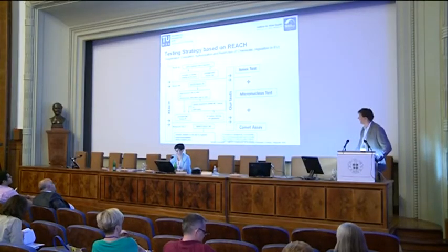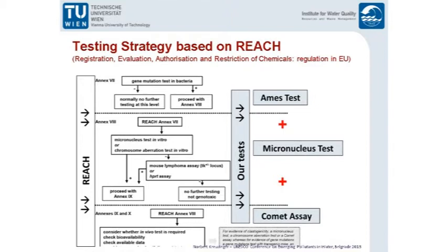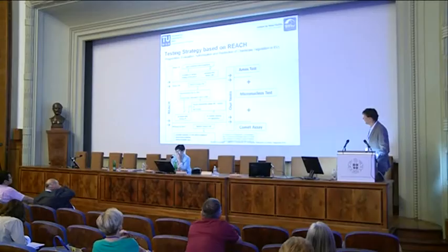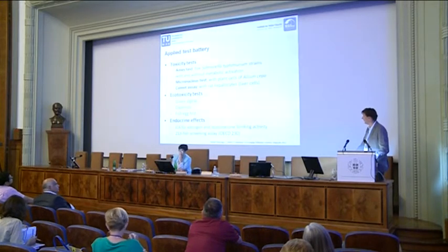just at that volume, because it makes a big difference in the cost and operation what additional treatment step you would have to implement. I spoke briefly about the tests that we need, and what could be one approach: you somehow link up to REACH, the registration, evaluation, authorization, and restriction of chemicals in the EU. They have a certain test procedure for chemical safety. And what I was doing, wastewater is considered a chemical substance released to the environment, and I took the same biotests as in REACH to look at the effluents and the ozonated waters for testing.